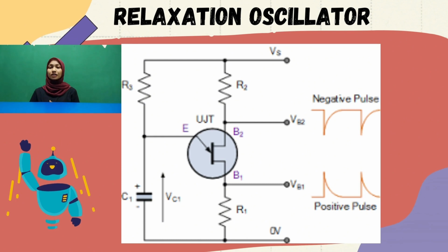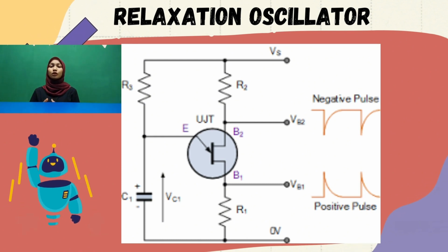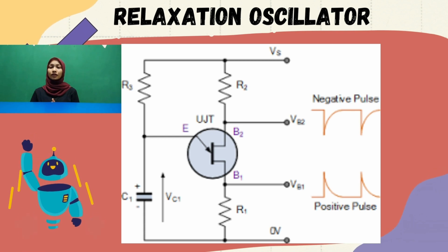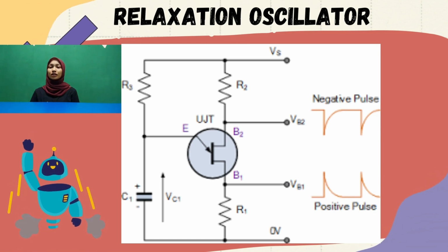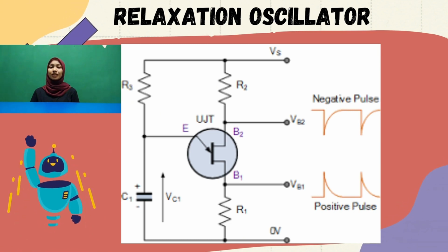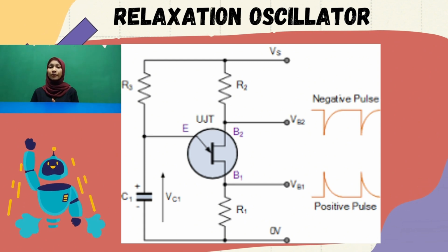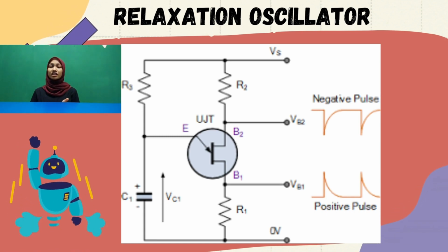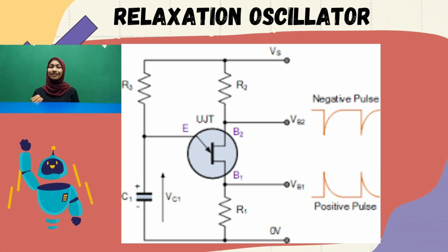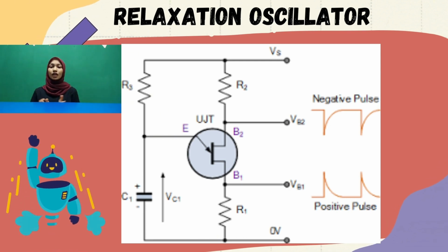At the core of a relaxation oscillator is the interplay between the charging and discharging cycle of a capacitor. The transitions are triggered by a threshold voltage, and the circuit typically involves components like resistor, capacitor and a switching element such as a junction transistor or operational amplifier. Now, where do relaxation oscillators find their application? They are commonly used for pulse generation, timing and clock generation in digital systems, and even in frequency synthesis for communication systems.